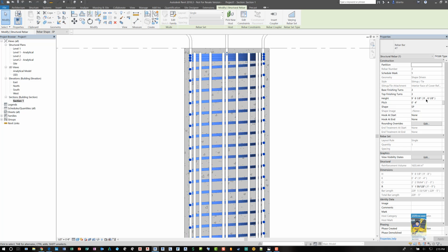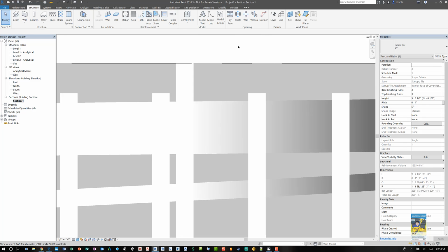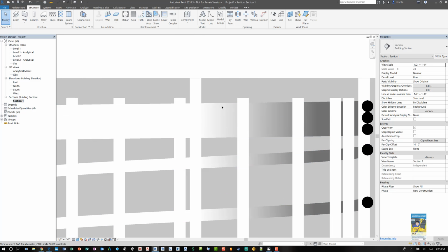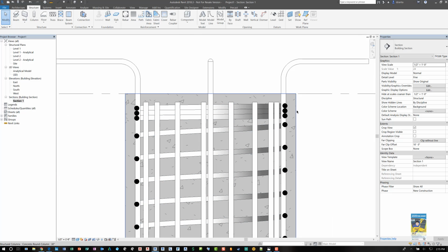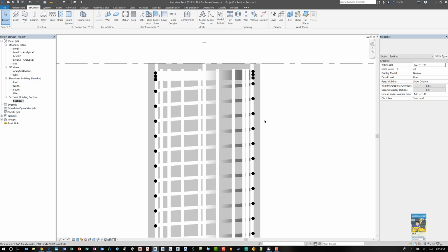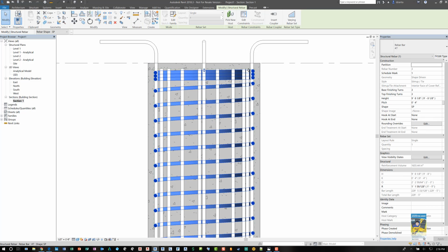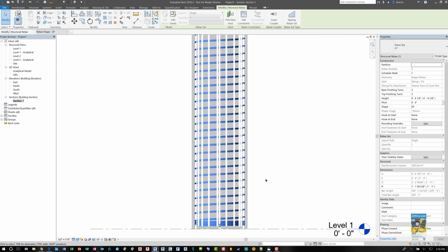And then there's a height here, and that's going based off of the rebar cover. You see how there is a green dashed line that covers the outside edge of the column. That is there to let you know the rebar cover has a restriction, and so it's abiding by that. That's why you can see the green dashed line when the rebar is selected, and it says it's 9 feet 8 and 1/8 of an inch because it's accounting for the top and the bottom instead of being 10 all the way through.